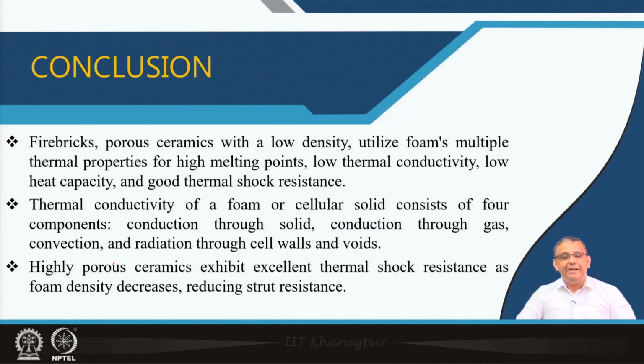Okay, so that brings us to the conclusion for today's lecture. We have seen in this lecture that for porous ceramics, the thermal properties are very important. There are many properties that we can consider, like the melting point, the expansion coefficient, the specific heat, the conductivity and the thermal shock resistance. We learned that both melting point and expansion coefficient are not dependent upon the porosity, and their values are similar to the bulk material of which the porous body is made, while both conductivity and thermal shock resistance depend upon both the amount of porosity and also the pore shape.